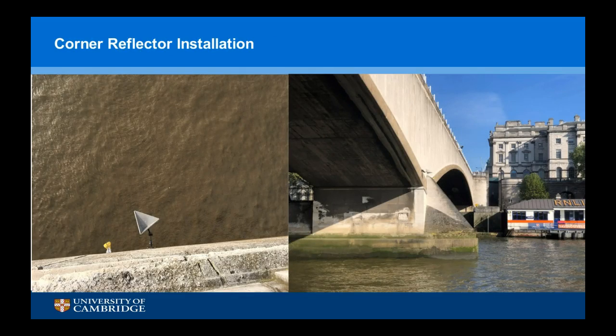At each of the prisms, next to each of them, we installed a corner reflector. A corner reflector is essentially three pieces of metal that help the radar reflect and bounce back, and then you get a much stronger amplitude reflection. They're pretty cheap, and these ones were designed to be made out of aluminium to be a little bit lighter, and are perforated to allow water drainage, anything like that.